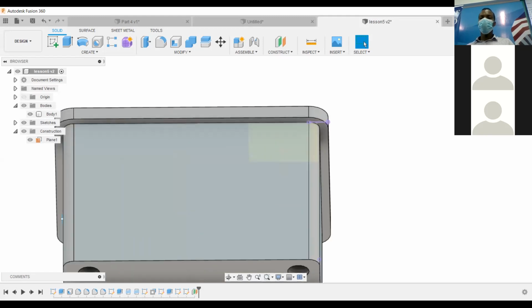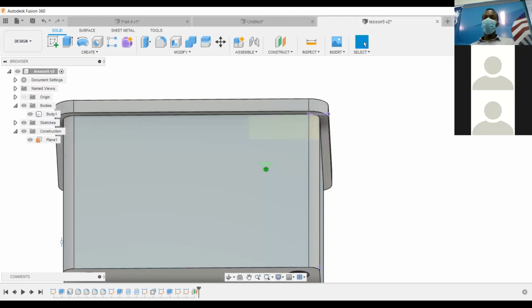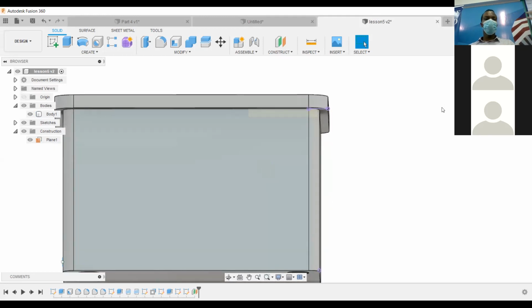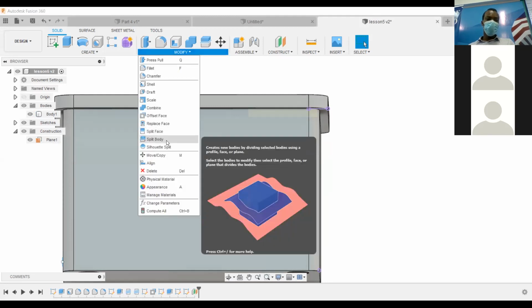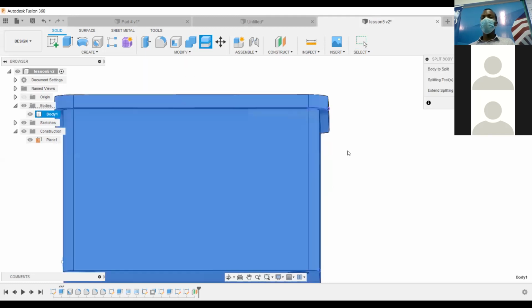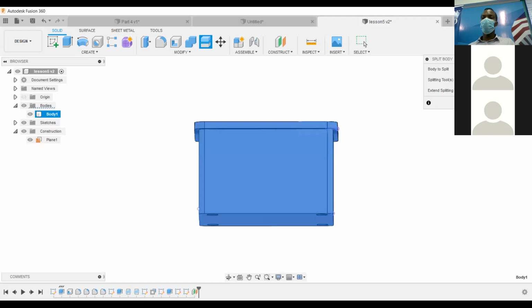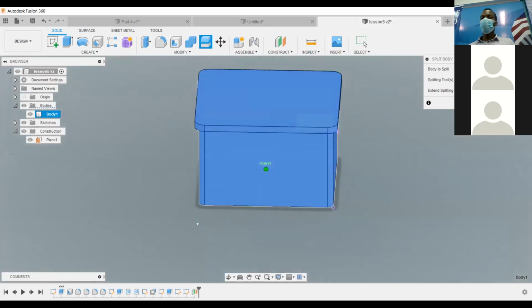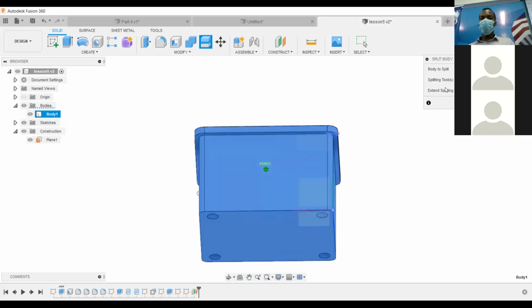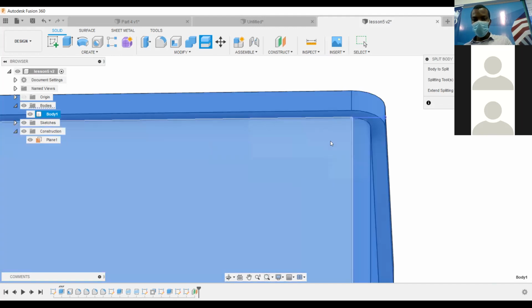Once you do that, even you guys who didn't have a lead, I want you to offset with even 20 or something, so that I show you how to cut. Offset with a value of 15, 10. Then we want to slice the 2 parts, or divide them, using that plane. So you come to modify, split body, then you click the entire 3D object, the one we have. Then select the splitting tool. The splitting tool is our plane, which we had selected.